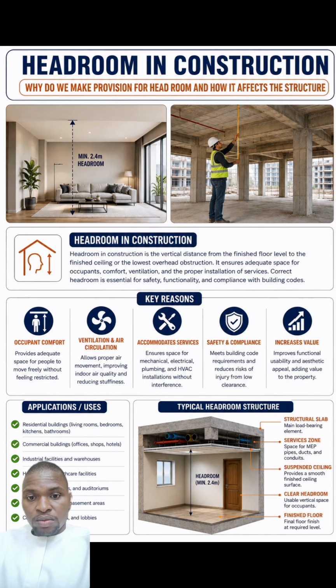So headroom in construction is the vertical distance from the finished floor. When they say the finished floor, it includes your DPC, it includes your floor finishing, either your tiles or whatsoever you decide to use on your floor finishing.